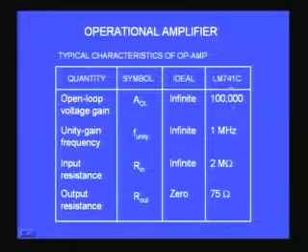It is an enormous gain. This is actually the gain factor. The relationship between the output voltage and the input voltage is 100,000 in the case of the 741. We saw that even to get some 20 to 100 with transistors we have to put a lot of effort and then analyze it using h parameters and all that. So it takes enormous effort to design even a gain of 100 or 200 in the case of transistors, but you find here with an integrated circuit form you can very easily get a gain of 100,000 by special circuit design.